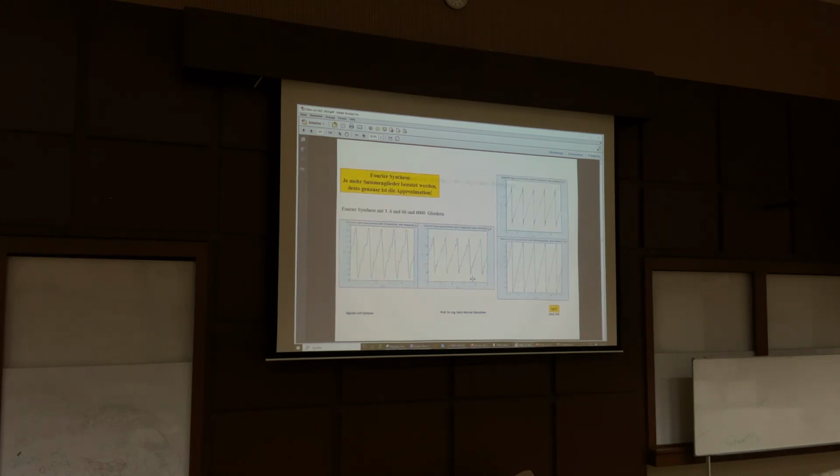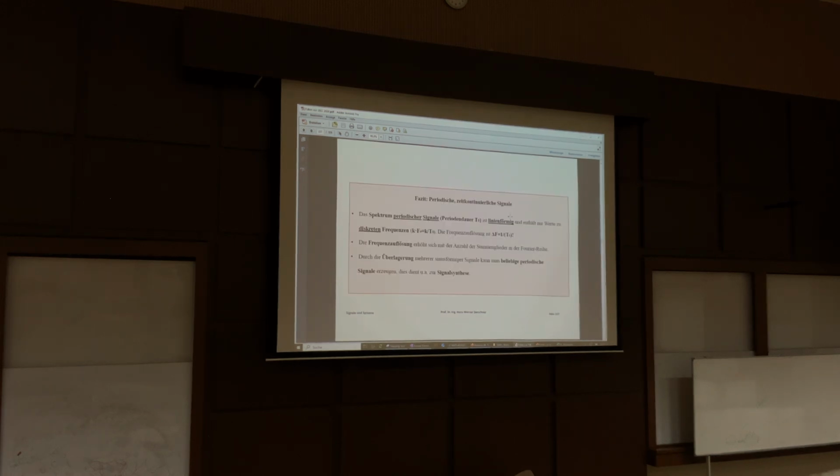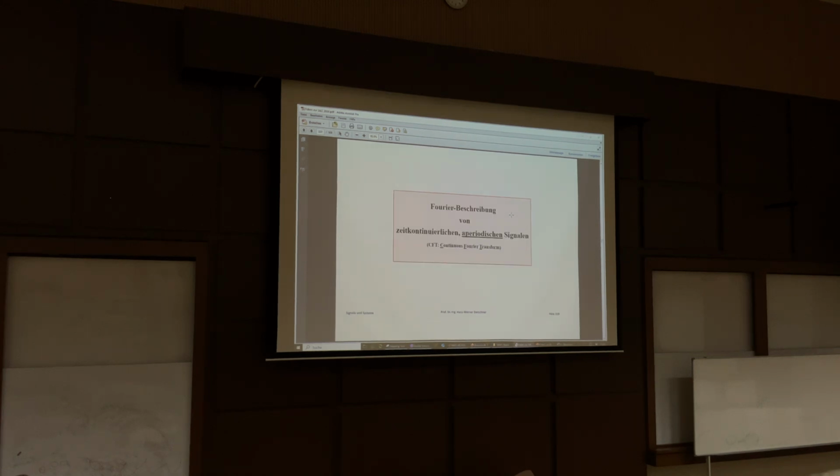That is, in the end, we reproduce the sawtooth signal, which may come in with a completely destroyed shape, and we know, okay, this is a sawtooth signal with the different frequencies. These frequencies we sum up with the CKs, which come from the analysis, from the spectrum, and we get the signal reconstructed. Okay, so far so good. That is the periodic signal synthesis.